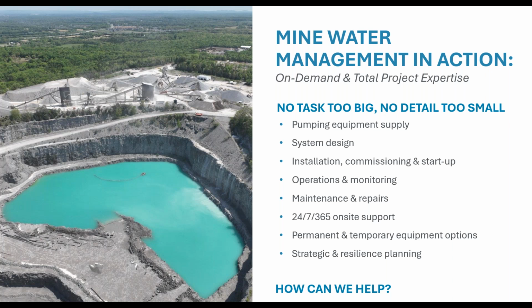They don't typically require additional infrastructure. If it's a well-maintained sump, it could set on the bottom of the sump. Although, we are seeing a lot more applications where they're floating the pump, again, to help reduce the concerns of clogging.